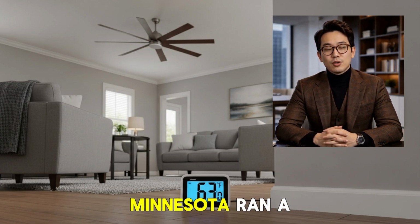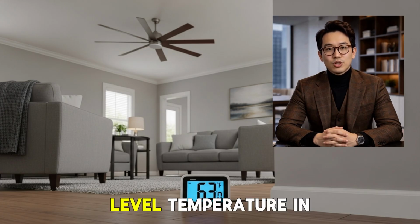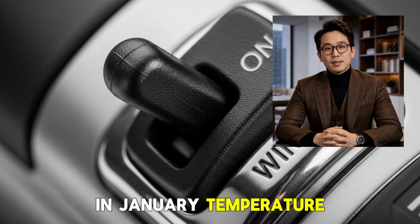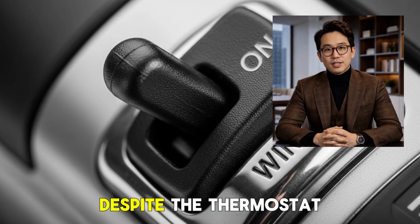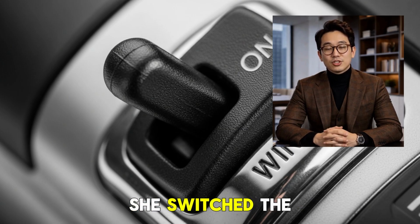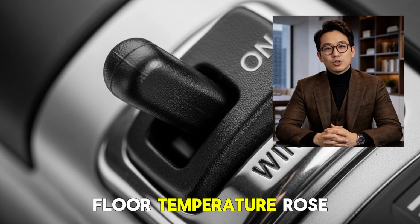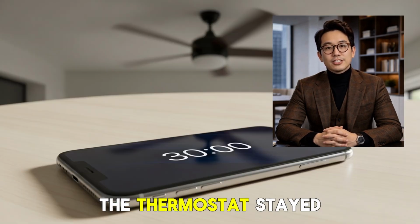A homeowner in Minnesota ran a simple test. She measured floor-level temperature in her living room with the ceiling fan running counterclockwise in January. Temperature at ankle height was 63 degrees, despite the thermostat set to 70. She switched the fan to clockwise rotation and let it run for 30 minutes at low speed. Floor temperature rose to 68 degrees. The thermostat stayed at 70.